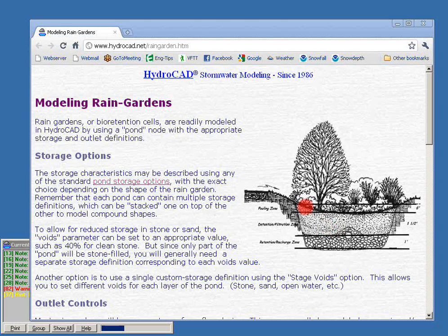And in that scenario, you may want to have enough volume that you can actually retain that entire volume in the above-ground space, so that if you suddenly get that inch of rainfall, there's no time for it to infiltrate. You want to be able to capture all of that and leave it time to infiltrate through the layers below, which will take hours to days. A typical rain garden is not a rapid infiltration structure because you're trying to treat the water as it flows through.